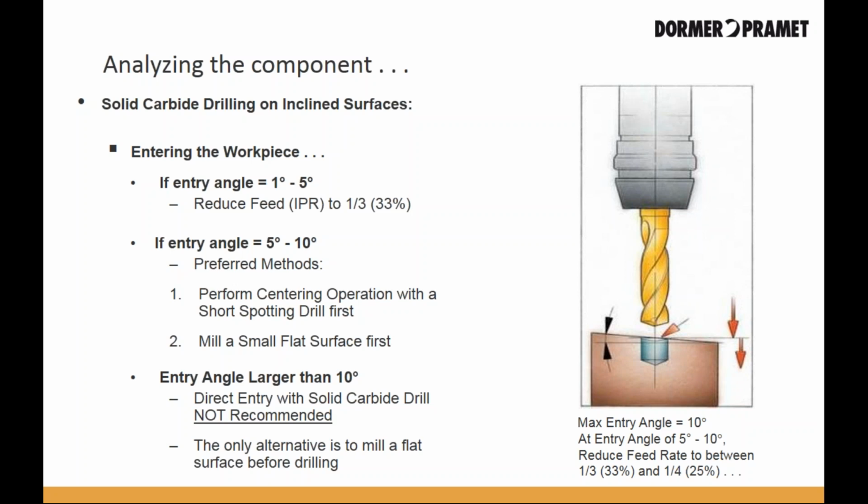If you encounter any angled surfaces greater than 10 degrees, do not use a solid carbide drill on this unless you mill a flat surface perpendicular to the center of the drill first.